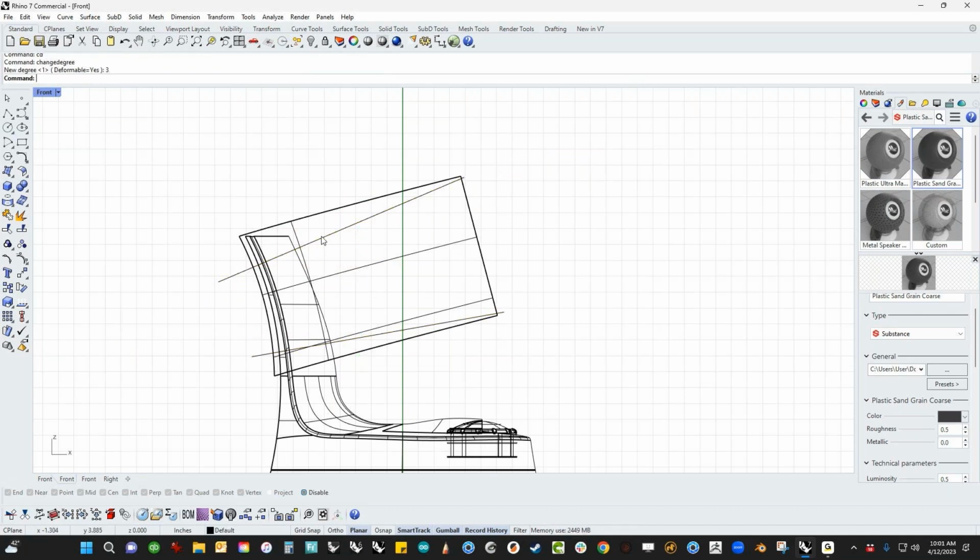And I'm going to grab the points of this one. I'm going to pull it up a little bit to give myself some shape. Same thing down here, just pull these two down. I can't overemphasize how useful that 4-point line is, because it really allows you to generate really clean, really nice, really useful curves that are balanced. The parameterization on them is really good and all that kind of stuff.